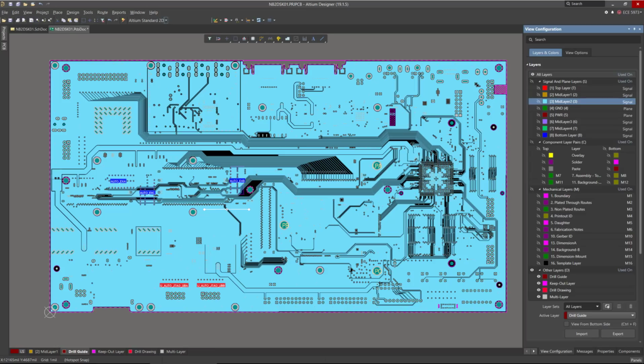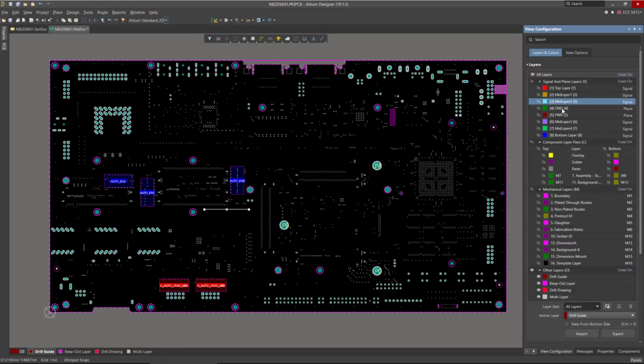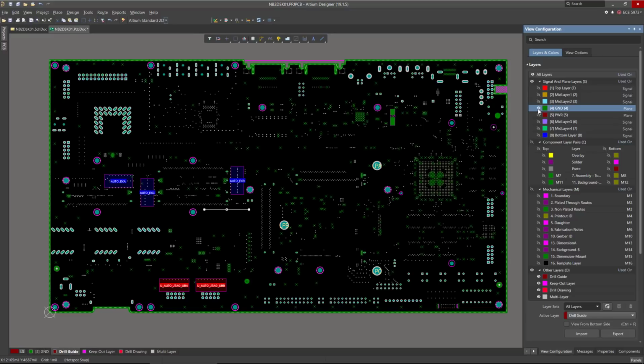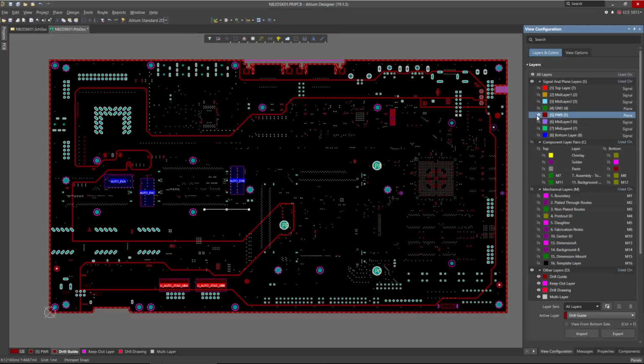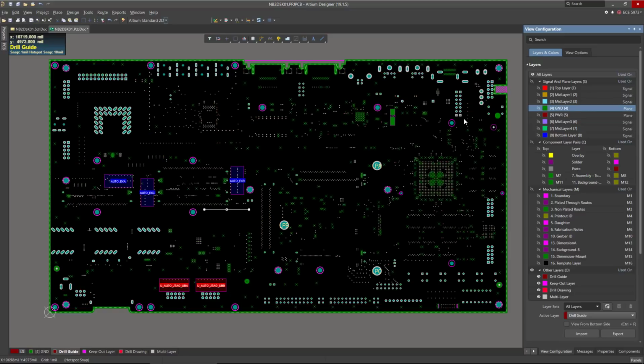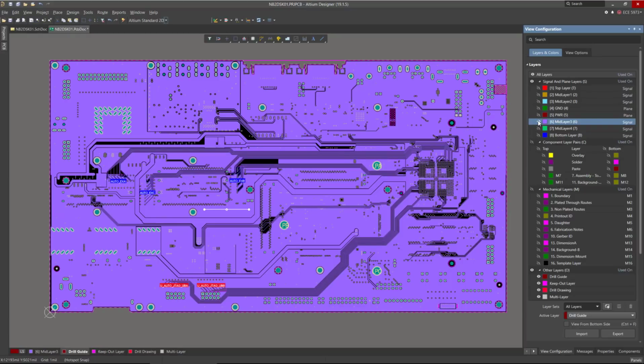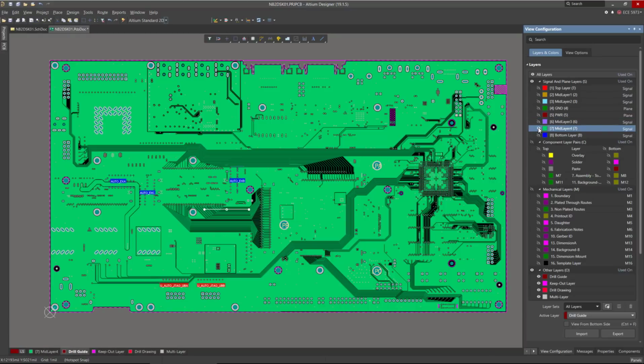So this is the third layer. Now they have plane, as you can see. We will talk about the planes. This one is ground, and this one is power. Basically, these planes, everything is filled with copper. There is no etching. It's like the copper foil without any etching on it. It stays as it is, and the vias connect from different parts into this plane layer. So here is layer number 6, layer number 7, and they have so many traces.